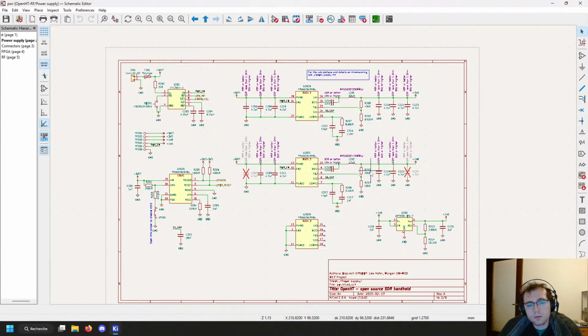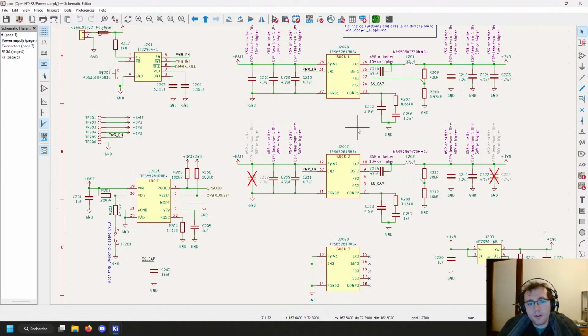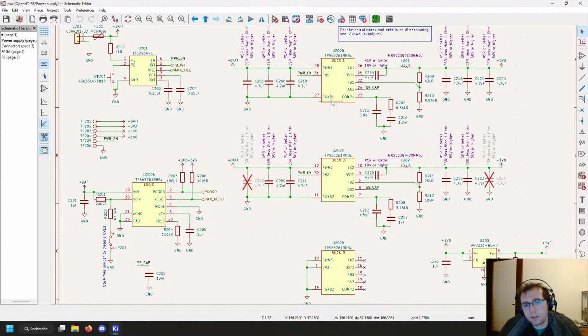It turns out that there are not that many buck converters which can run with that input supply voltage. Also these devices tend to have bad efficiency at light loads, because of the switching of the MOSFETs and so on, you lose a lot of energy for very little energy output. And so of course this crashes the efficiency.